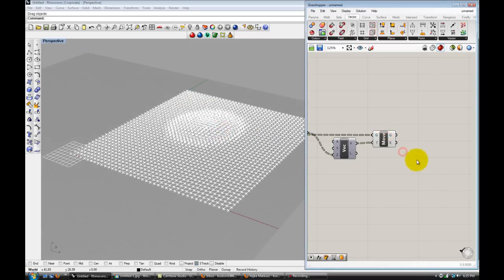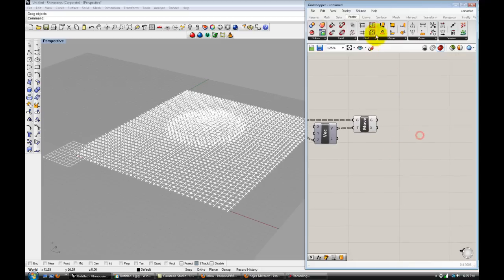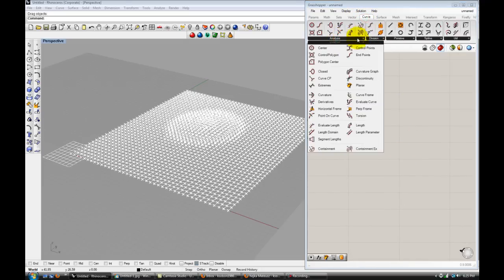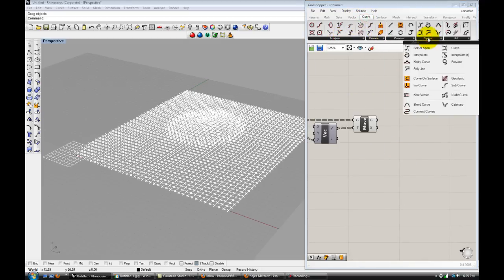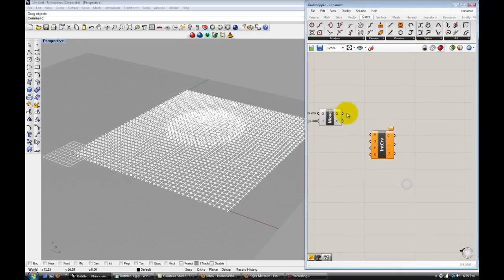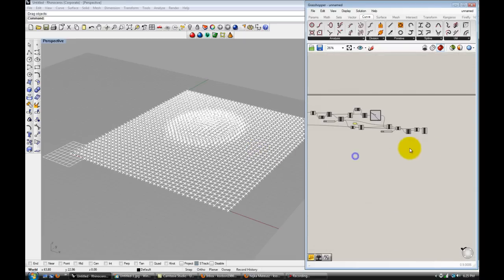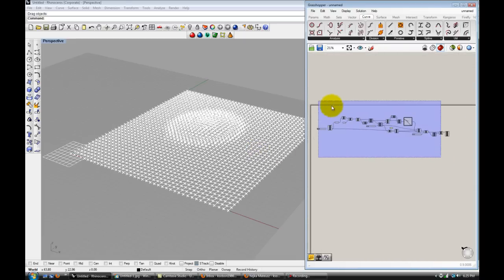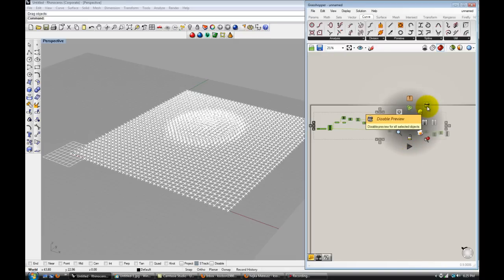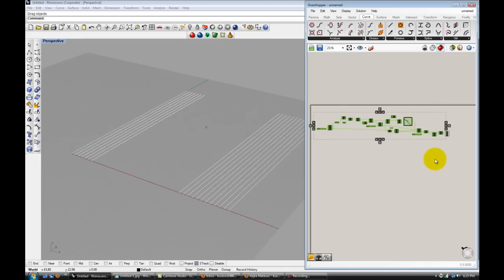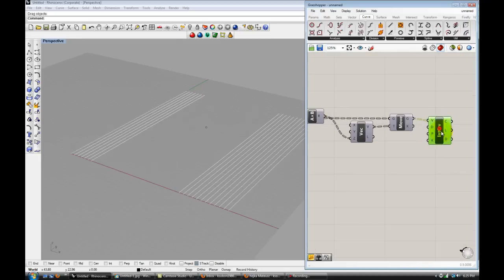And to better visualize that, I'm going to bring the curve under spline interpolate. I'm going to make curves out of this. And I'm going to select all this, and if you push down on your scroll button, it'll bring up that graphic, which is going to allow you to change a few things here.